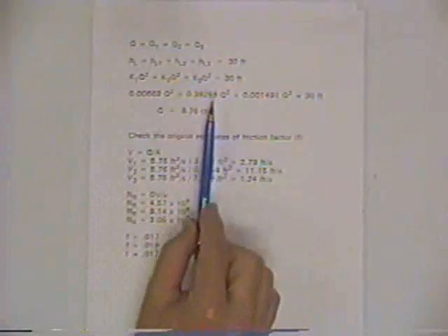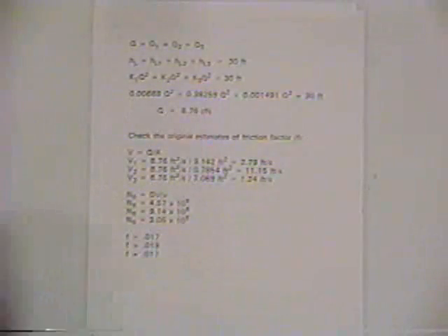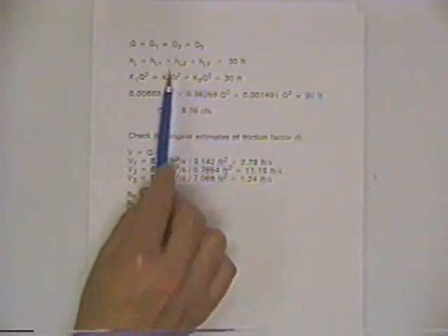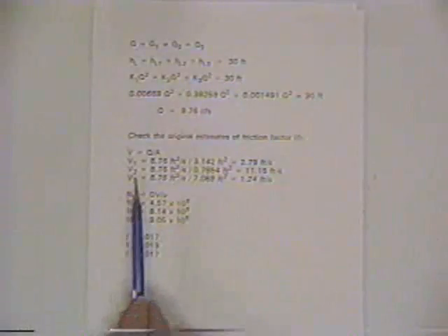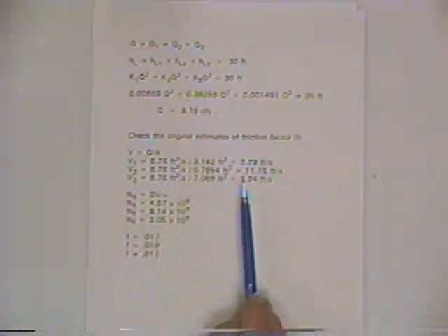On the previous page, we computed the Ks, which is saying we applied the Darcy-Weisbach equation, and we compute the Q. So it's basically the same problem we had before. We just had to recognize that we're summing the head losses and the Q's are the same in the pipes, which made for a little more computational effort. Same thing as the previous problem: once we compute the Q, we can get the velocities, and after we know the velocities, we can compute the Reynolds numbers. Then knowing the Reynolds numbers, we can go back to the Moody diagram, which we've been using, to confirm the friction factors. So, same type of problem, we've just got pipes in series added into the problem.